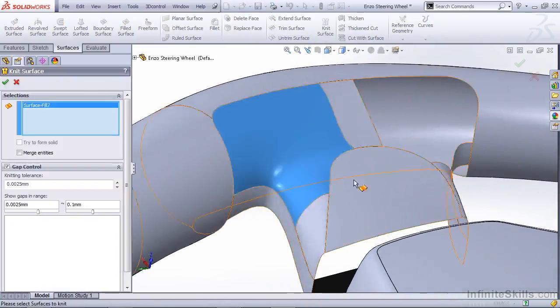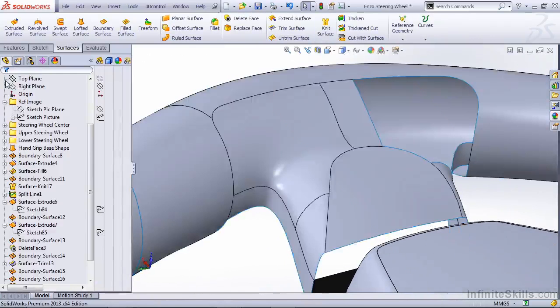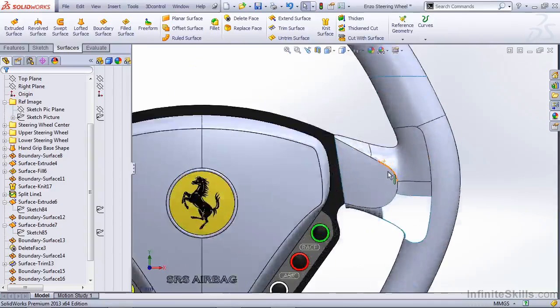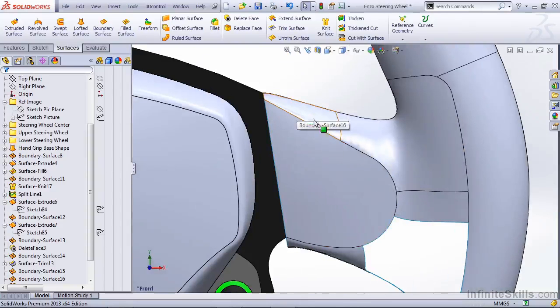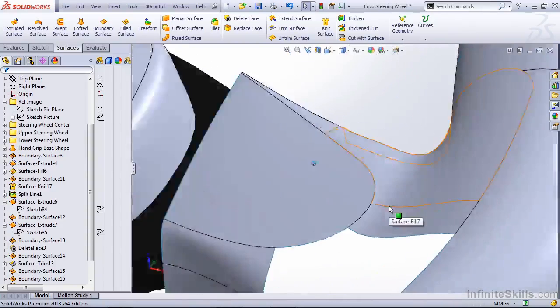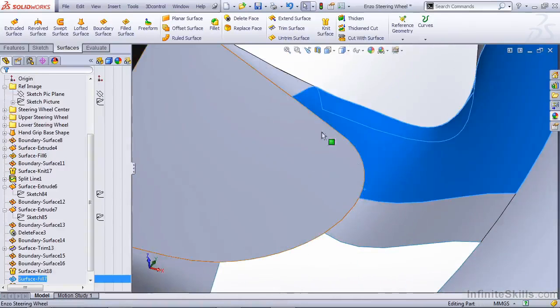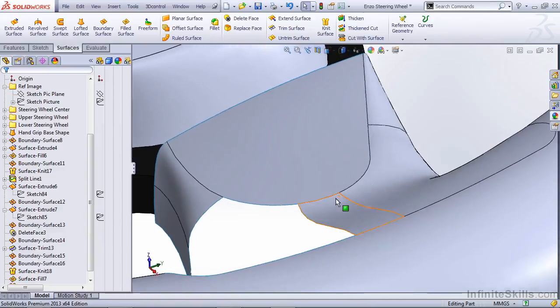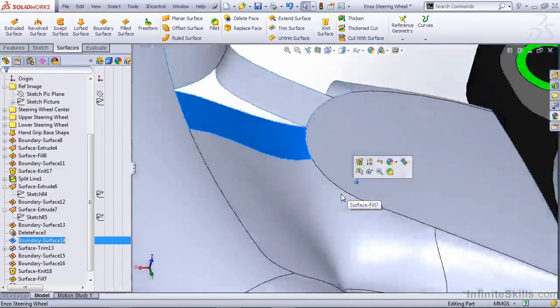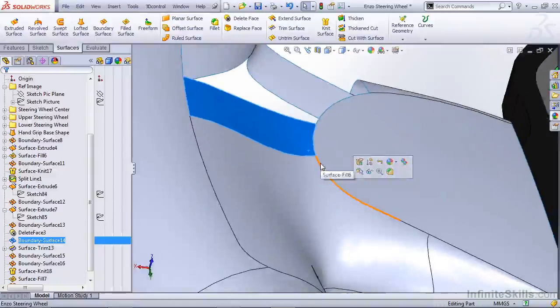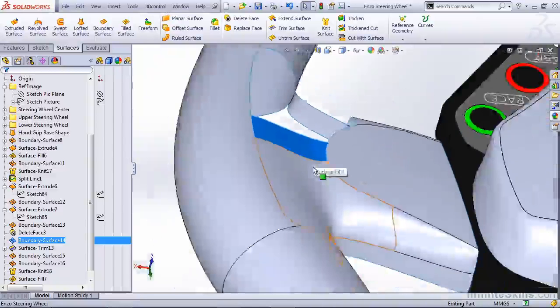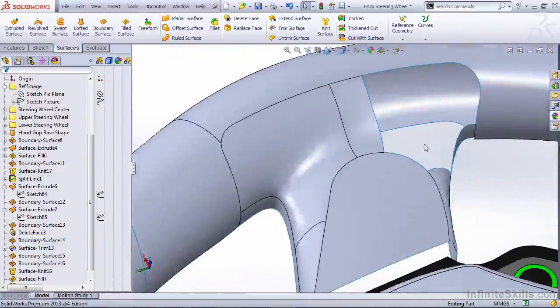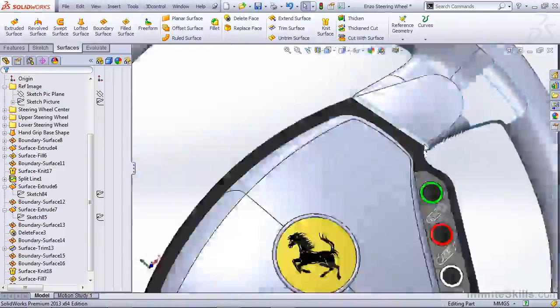I'm going to go ahead and knit this to the surrounding surfaces. That way we have one created. So you can see that blend worked rather nicely. Everything worked out well, and the tangency is carried on through all the edges. It's very important when you're creating these filled surfaces, if you use something like that 10-degree tangency here, to make sure that you understand when you apply relations, it's going to try to override that and introduce a lot of tension into the surfaces, especially in this corner. So it's important to remember what you did, when you did it, and why you did it.